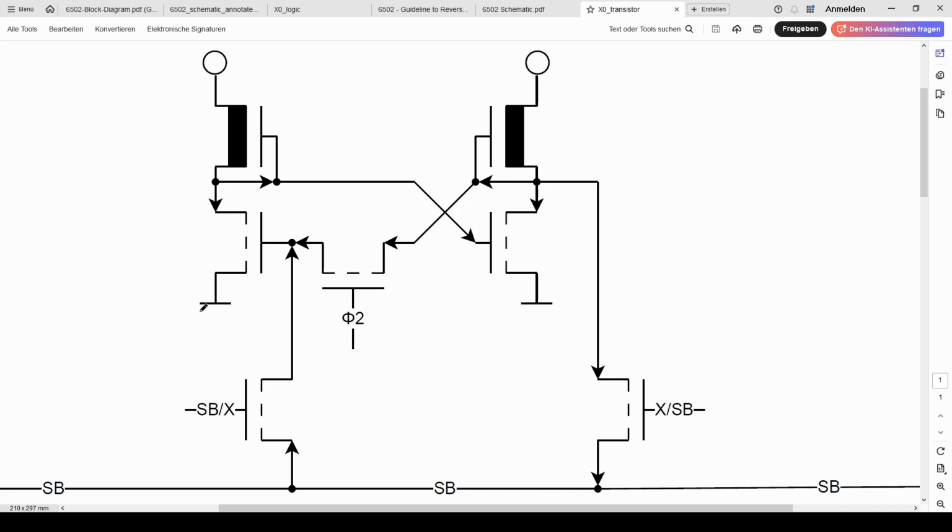So let's just work through what this would be like, before we introduce any values from the bus. Once again, we're 0 at first, and this here is the output line. If we follow that in this direction, this is 0 here, and so this transistor doesn't conduct, which means that because there's always power from here, but it can't get through here to ground, it instead flows through this line into the gate of this transistor.